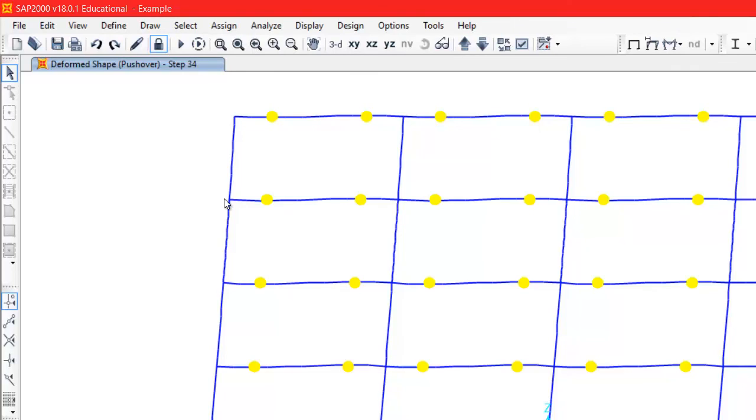No questions at all? If we want to not consider the PZ, we have to set the initial pushover to 0, right? Because we start from the end of the graph. You don't want to include the P-delta? Yes. If you don't want to include it, don't model the leaning column. Or actually model the leaning column, but just sum up those shear forces.